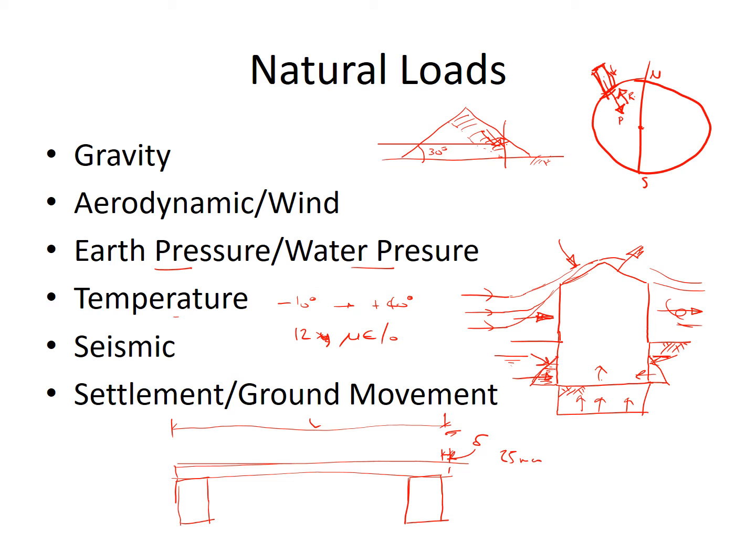They are essentially equivalent to the force required to compress this deck by 25 millimeters. And these are big structural elements. They have quite high stiffnesses, in terms of the Young's moduluses involved. We need really big loads to compress a bridge deck by that amount.